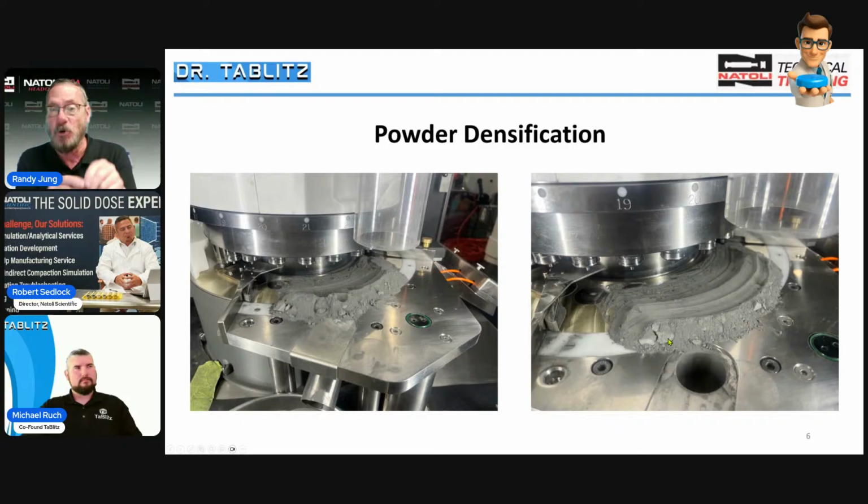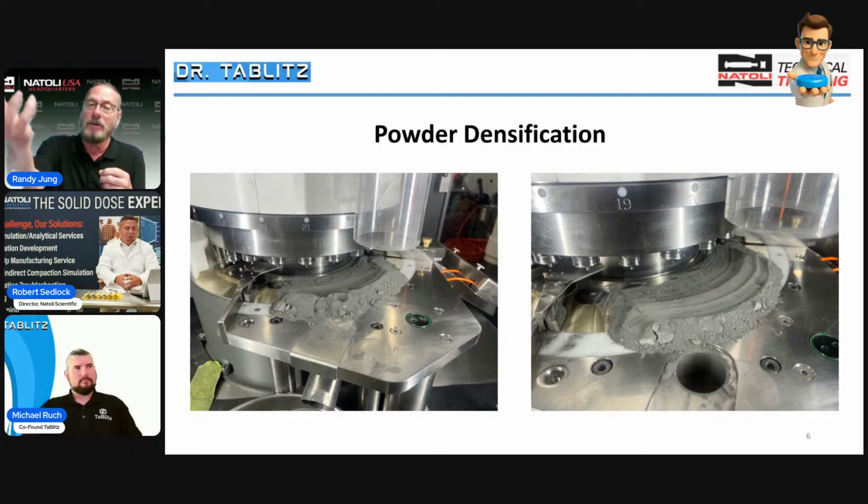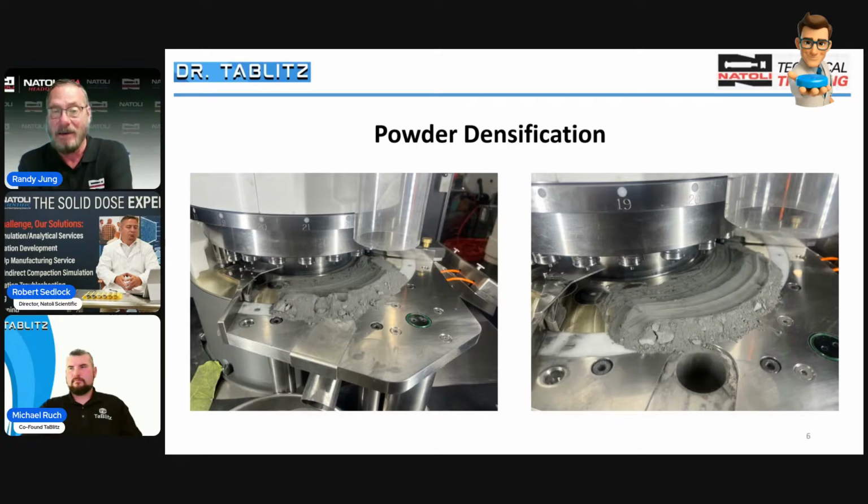In this case, I'm doing it before I put it in the die, and that's why it affects weight. In the other case, it can affect hardness, just because the molecules don't react the same way. But in this case, I'm literally affecting weight because that denser material is now in the die, and it's not consistently the same in every die. Right. And the effect of pre-compression is that when your particles are closer together, you've got more contact surface area for better bonding points. So the particles bond better when they're closer together. That's what you're explaining there.